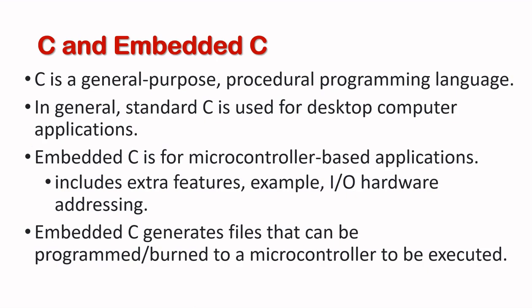Now, embedded C is targeting really microcontroller-based applications. And it includes extra features, for example, input-output hardware addressing. And it also generates files like a hex file that can be programmed or burned to a microcontroller so that it can be executed.